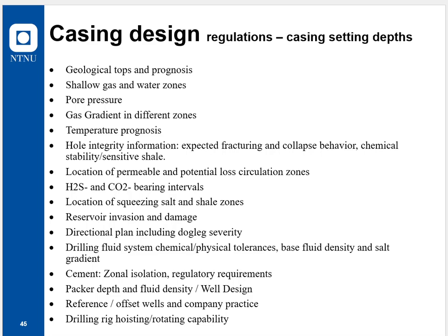It's just a place to start your analysis, and then yeah, we need to know that we can pull the pipe, like said earlier. If your company says that you need to be able to pull 100 or 150 tons above the string's weight, you need to know that the string weight plus 150 ton is still within the hoisting capacity of the pipe.